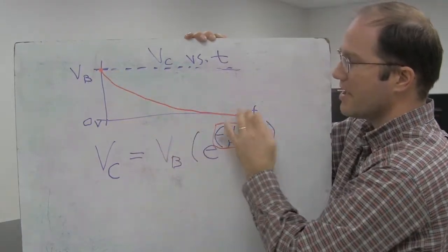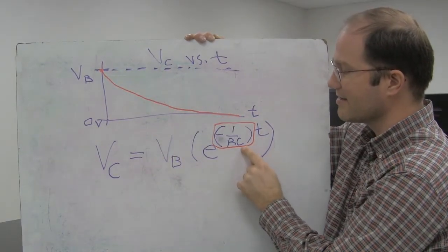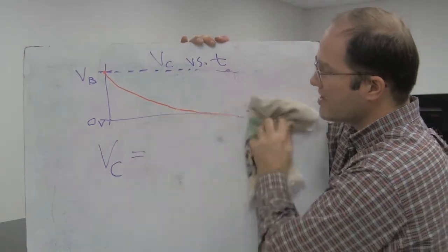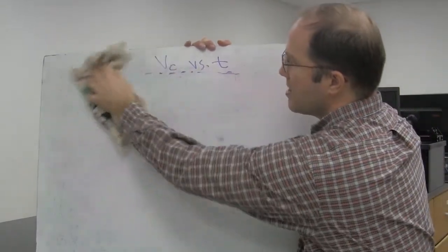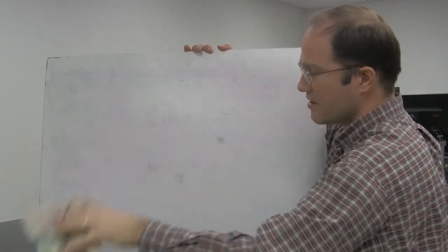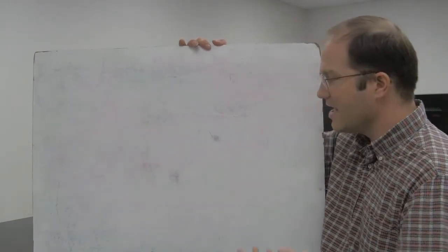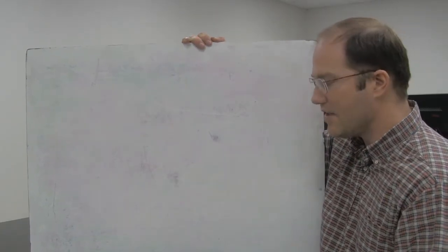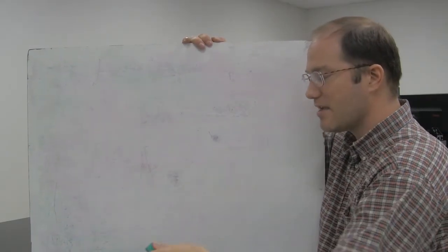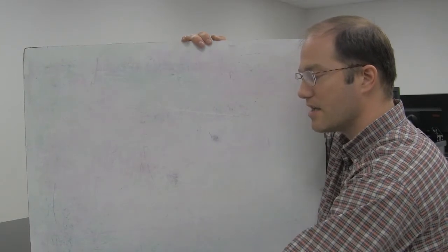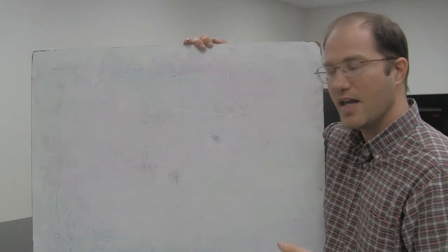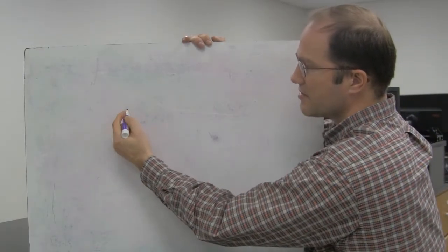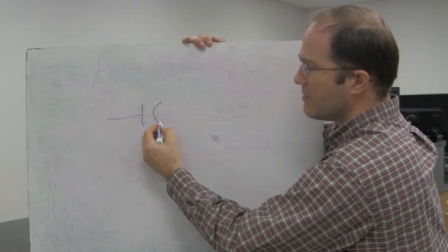So you do this experiment and then solve for C, the capacitance, and now you've got an idea of the capacitor that you have. And so you'll be doing this with two different capacitors. So you'll be discharging two capacitors, determining the curve fit parameters, and then you'll have two capacitors where you actually know the capacitance. And then we're going to use those two capacitors and say, well, what do we predict would be the total capacitance of a circuit if we put those in series or parallel? So let me draw this out. You have two capacitors, and let's say we put them in series.